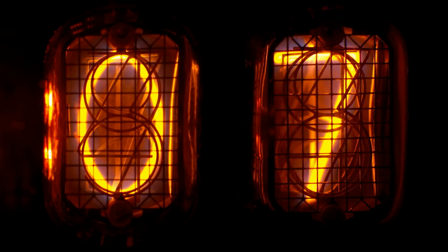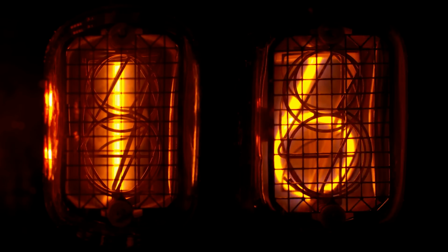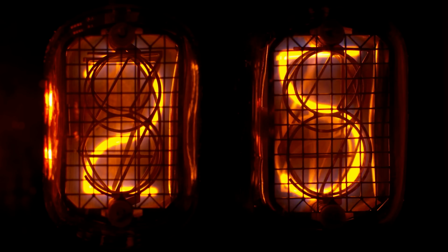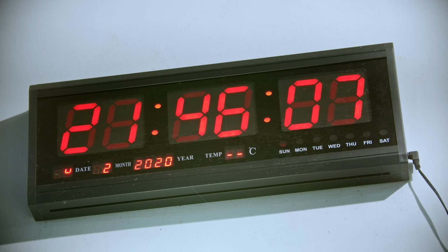Because of this, Nixies quite naturally attracted plenty of competition. But many of its contemporaries shared another of its flaws: the need for a dedicated output for every character it can display. Since Nixies use wire-form numerals, a standard Nixie tube needs 10 inputs to function, one for each of its cathodes. But a segmented display, which forms numerals by combining different shapes together, only needs one output per segment. That saves on wiring, but it also makes the circuitry which actually drives the display devices cheaper.